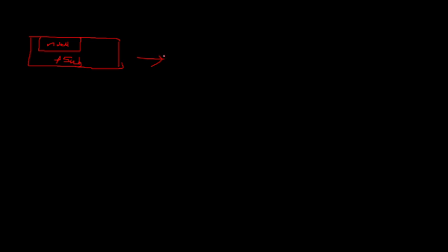In the second step, a thick layer of SiO2 will be deposited all over the substrate. So this is your P-type substrate and N-well. A thick layer of SiO2 is deposited all over the surface, but because thick oxide is required only for the source and drain regions, we make it directly. This is, suppose, the source, and these are the drain regions, and this is again the source of the NMOS, and this is your N-well.